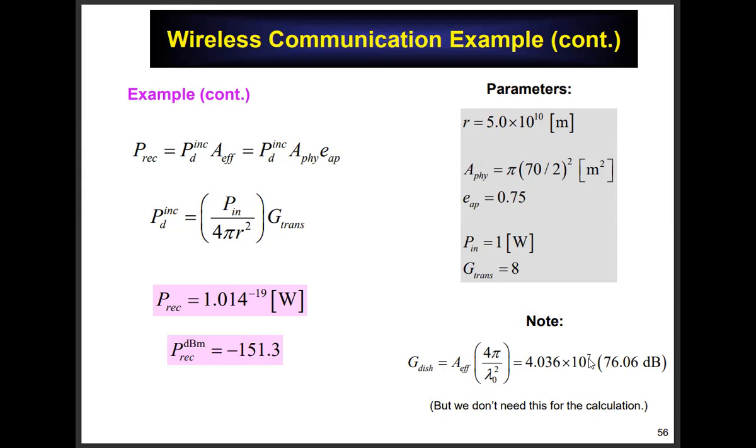Now remember, wire antenna, 1.643. The gain of this Goldstone dish, 40 million. You see why NASA likes to use huge dishes to communicate out in space? You need that extremely focused beam to really be able to receive good signals or to transmit. If this thing's being used to transmit a signal to Mars, that beam is really focused right where they need it. You convert it to dB, 76 dB.